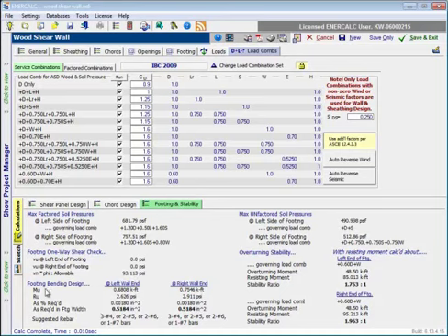The next category down reports the bending moment design information. It's presented at both the left end of the wall and the right end of the wall, so we can see a factored applied moment at both ends, an RU value that's reported, an area of steel or a percentage of steel, in this case it's an area of steel that's required, and then a recommendation for reinforcing bar patterns. So in this case 3 number 4s would do the trick, 2 number 5s or 6s, or even a single number 7 bar if you were so inclined.